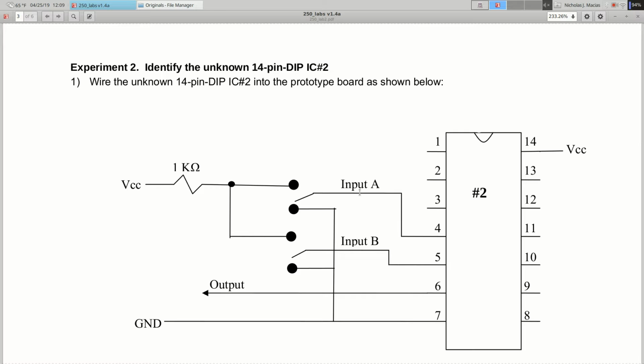It's got to be fed either 5 volts or 0 volts. The reality is, for this type of chip, if you don't connect an input, usually it comes out as a logic 1. But don't ever rely on that, because as power supplies fluctuate, that can go away. So make sure you're always connected to either 5 volts through a resistor or directly to ground to put in a 1 or a 0. So I think in some cases people had inputs floating, and the effect is that your zeros are basically treated like 1s, and then you get a really unusual looking truth table.